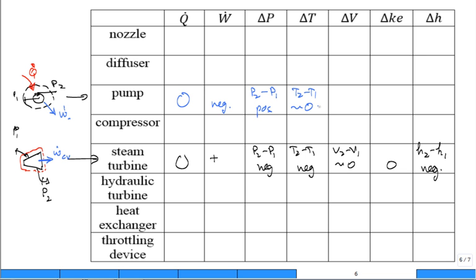The purpose of the pump is not to make the water increase in temperature. The purpose of the pump is to boost the pressure. Real systems, yes, there will be a slight increase in temperature. Even for an isentropic pump, a perfect pump. Okay, it's not just frictional heating. A great pump will still increase the temperature ever so slightly.